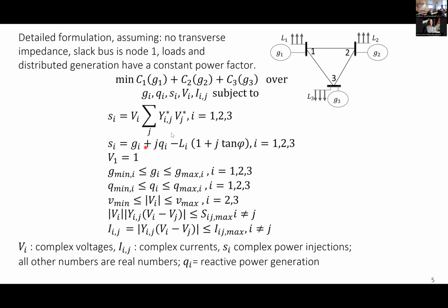That's the complex system. As you know, an AC grid needs one slack bus. Sometimes there are complicated systems with more than one slack bus, but in practice, an AC grid needs one slack bus here that dictates the voltage, sets it to a fixed value, and also has another function. By dictating the voltage, it has a side effect, which is probably the most desirable function. Which one is it? Well, it absorbs any difference in power. It balances the power in the grid.